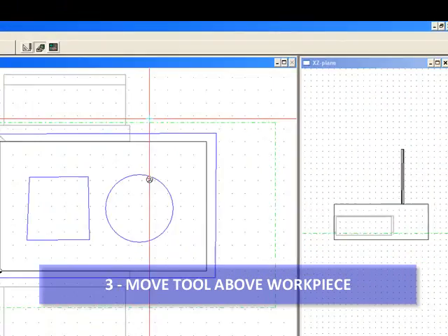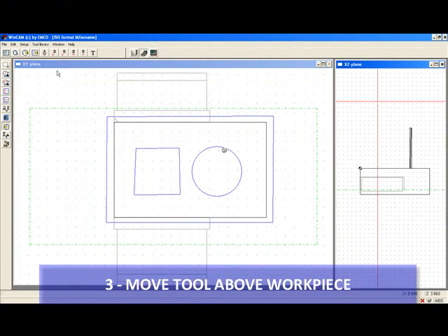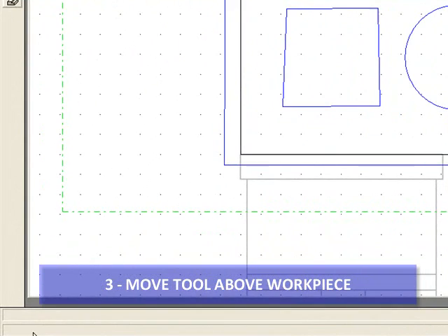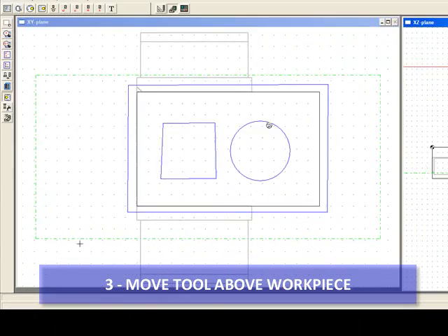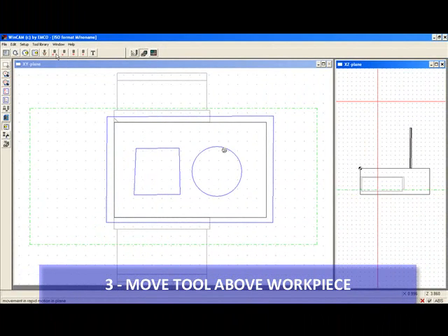So the way I fix that is I go up here to the menu, the machining menu. So I click on machining over here, and I'm going to click on the rapid motion in plane. Look down here and you can see it's gone right now, but when I mouse over that, you're going to see the different selections come up, or the different explanations of what each tool does. So I want the rapid motion in plane.